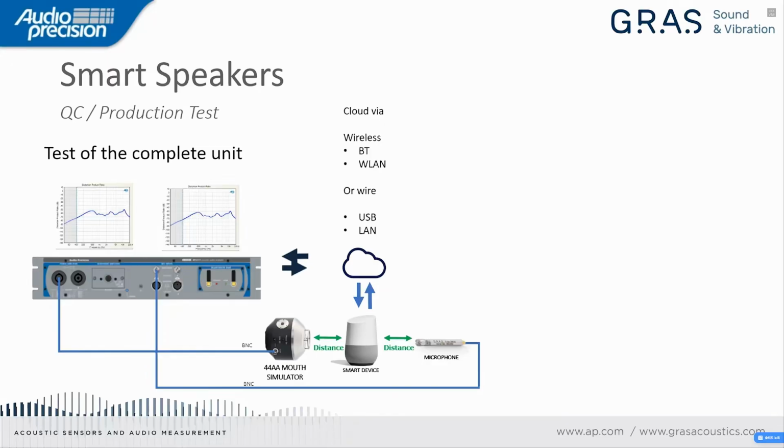If we are going to make a full test of our smart speaker, a full test as we actually do it in the production line, then it is actually a setup like the one we have here, where again we have a mouth simulator for sending in commands and test stimuli to our microphone array in the speaker.